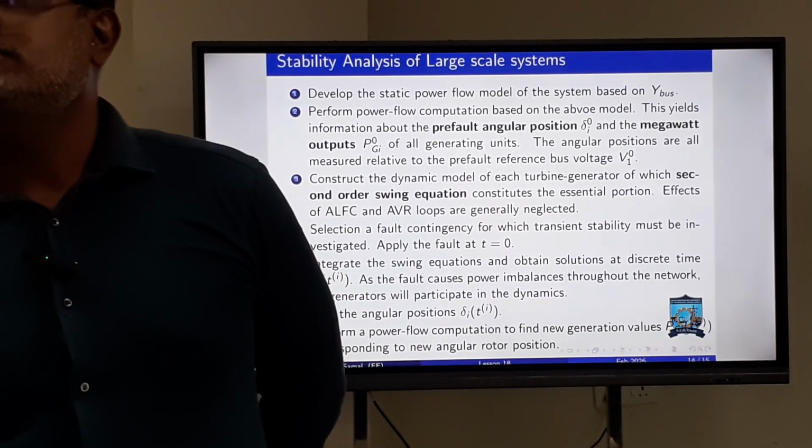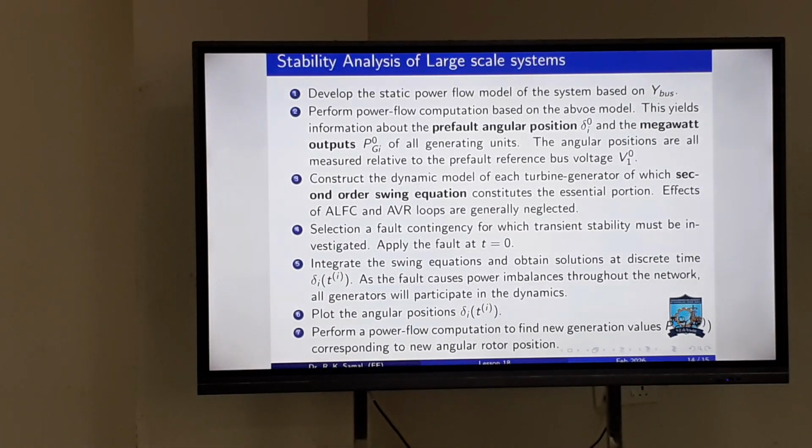What information do you need to perform this kind of study? Generator inertia constant, right? That is the only information that you need to perform the stability study, regarding the generator parameters. So suppose you go and do a PhD in the stability area, any kind of system, you need the generator inertia constant.